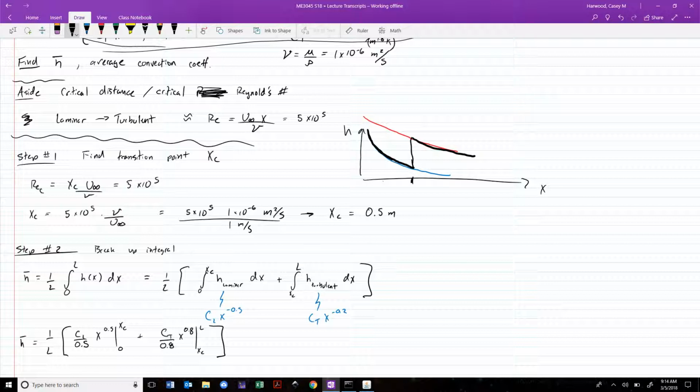With the viscosity decreased, our Reynolds number at a fixed position in space would tend to increase, meaning that transition would occur earlier or later? Any takers? Earlier. It would occur earlier, so we would make this jump not at this position, but somewhere upstream of that.